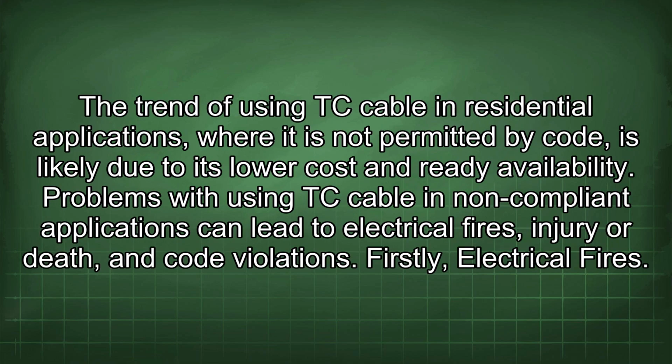The trend of using TC cable in residential applications where it is not permitted by code is likely due to its low cost and ready availability. Problems with using TC cable in non-compliant applications can lead to electrical fires, injury or death, and code violations.